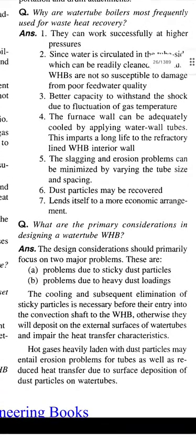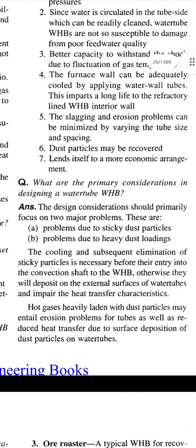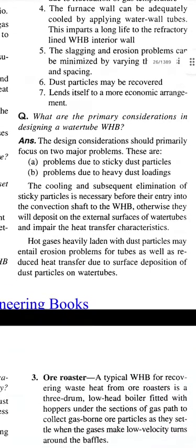Next question. What are the primary considerations in designing a water tube WHB? Answer. The design considerations should primarily focus on two major problems. These are problems due to sticky dust particles and problems due to heavy dust loading. The cooling and subsequent elimination of sticky particles is necessary before their entry into the convection shaft of the waste heat boiler. Otherwise, they will deposit on the external surface of water tubes and impair the heat transfer characteristics.